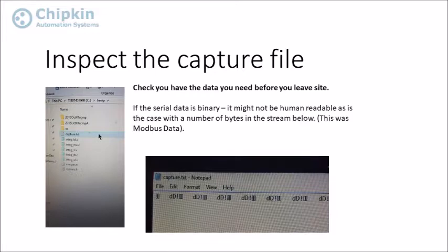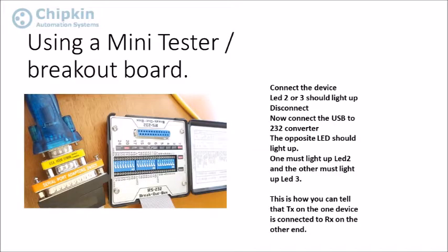What should the data look like? It's hard to say because there are so many different protocols. But chances are it's not going to be mostly human readable. You'll know you've got a decent capture if you can see some kind of pattern in it. If you feel unsure, call tech support and ask what a capture file should look like before you leave the site.